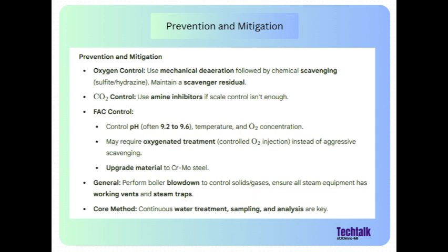Okay, now, let's get to what sounds like the most counterintuitive part, the oxygen paradox. Ah, yes. This is a big one. We've just established oxygen is terrible, causes pitting, yet the sources say zero oxygen is not actually the goal anymore. Correct. This is a major shift from, let's say, traditional boiler water thinking. For decades, the aim was get oxygen down to zero. But not now. Why? Because of FAC.